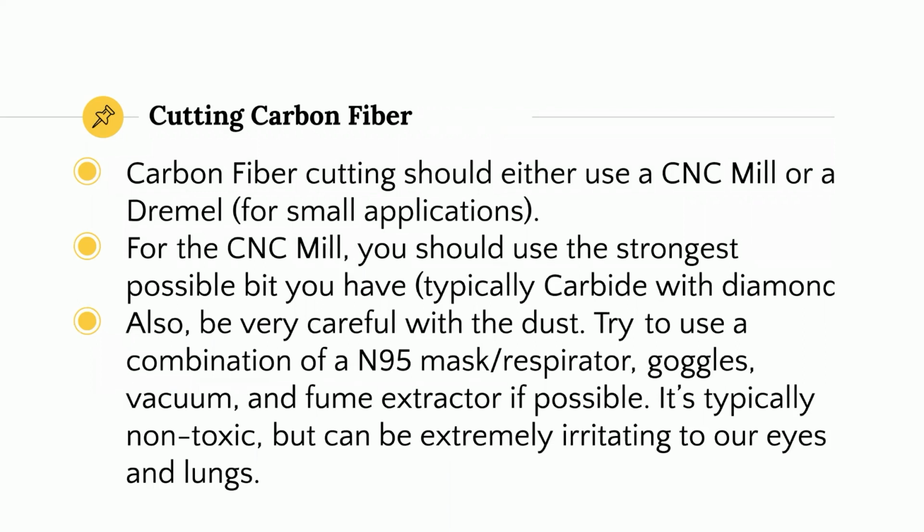So, cutting carbon fiber. Carbon fiber cutting should either use a CNC mill or a Dremel. The Dremel is mostly used for small applications. For the CNC mill, you should use the strongest possible bit you have. What I found is that you really want a carbide bit with diamond. This will be an extremely strong bit, and it is unlikely to break.